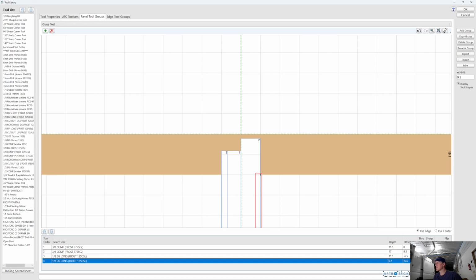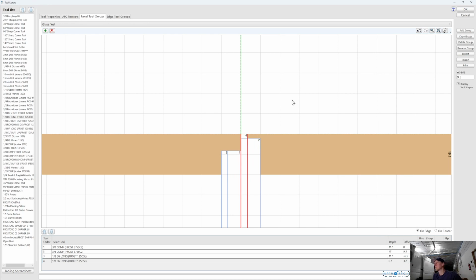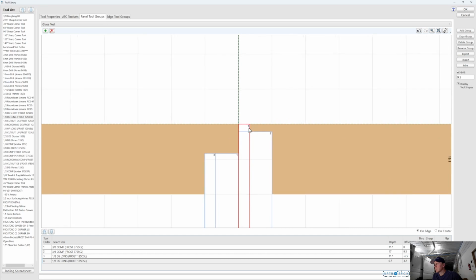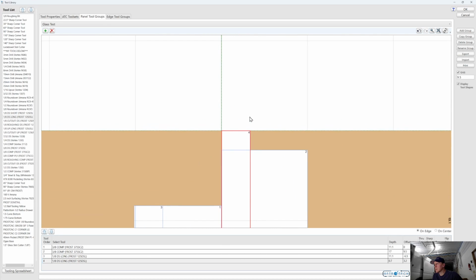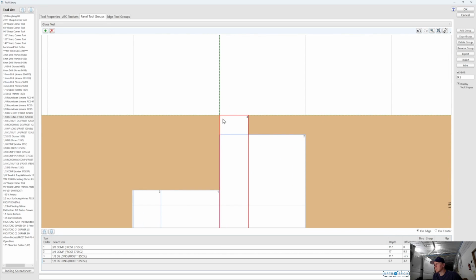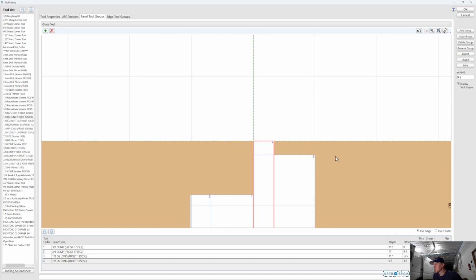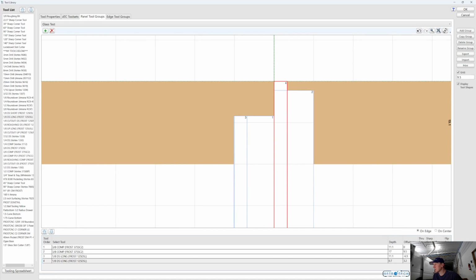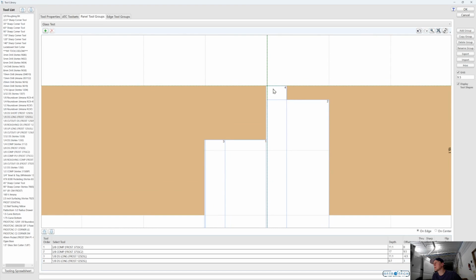This one's going to be a through cut. So click the through cut button. And the offset will be 3.2. And then we'll probably just stagger this a little bit as well, because you don't want to have a line there. If you don't stagger this, you will definitely have a machine line. So let's take this down to 3 even. That should be enough.